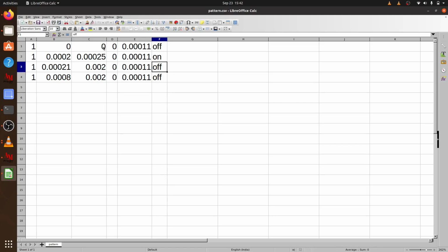So in this pattern, we are printing from point A to point B with laser on condition. Then we have provided a cooling time. For cooling, we take the laser out of the domain and we let the laser stay there for the cooling time. Cooling time we can provide by keeping the laser off for a certain time interval. In this interval, we keep the laser stationary or we can move it to the next starting point.